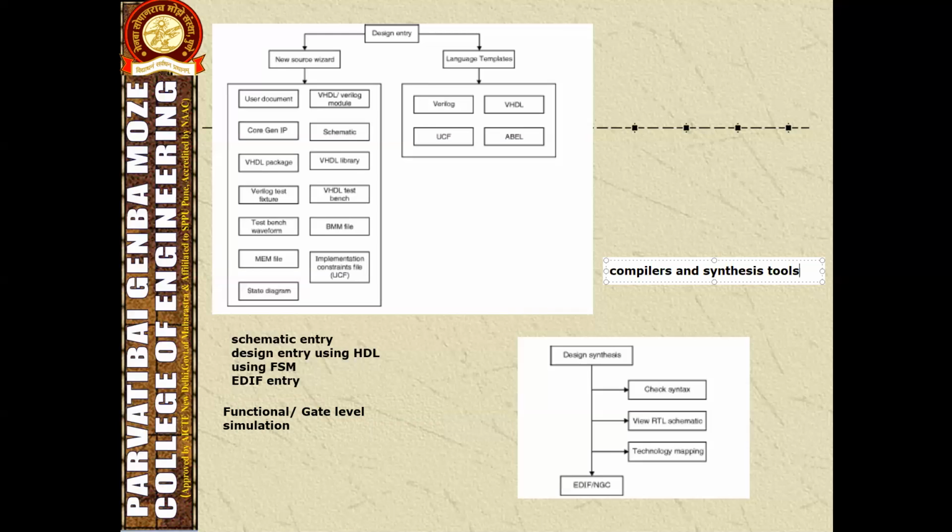In this stage, the HDL code is checked for syntax errors, and logic synthesis is the process that decreases the area or increases the speed of the design. Normally, the system designer develops the HDL code and the synthesis tool identifies the syntax errors. Here, this is the figure which shows the synthesis process. The synthesis process also creates the netlist.